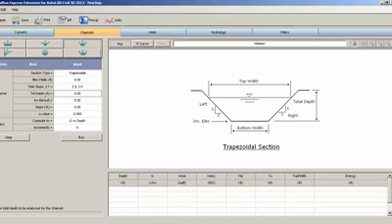And the top depth, from here to the top, is 2.5. And the initial elevation here is the first reading, if you go on site, where we have to specify the first reading in the level, which is the first elevation.